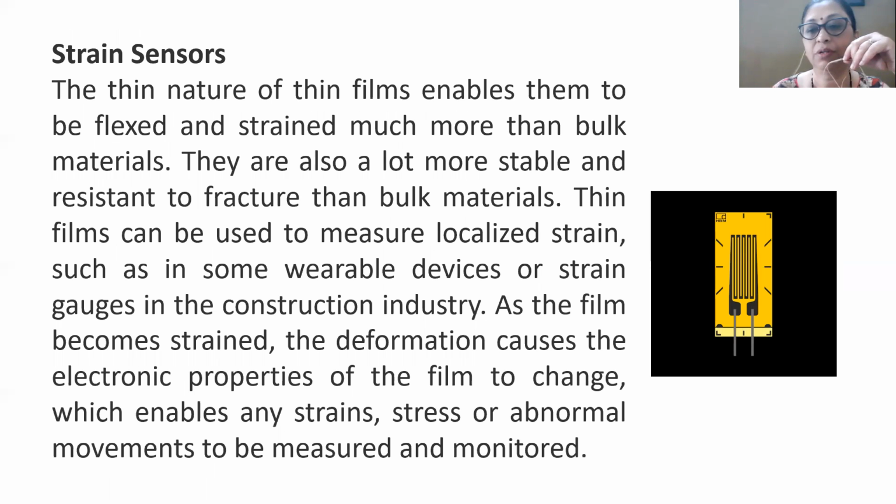One more thing you can observe here: this picture shows a strain sensor. Whenever you apply a stress to a material, strain is produced in that material. If you can measure this strain, then you are able to measure the weight that is applied, and even the pressure. Basically, thin films are suitable for such strain sensors.